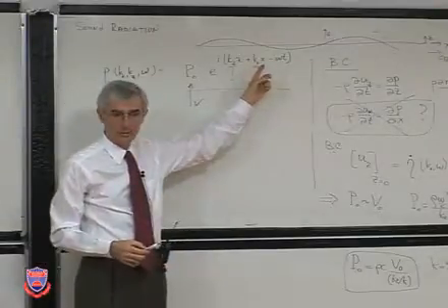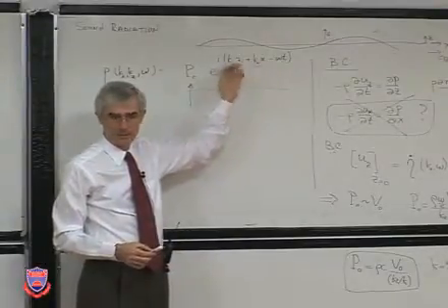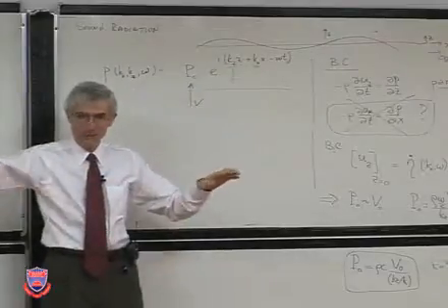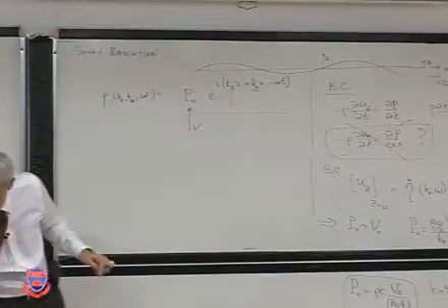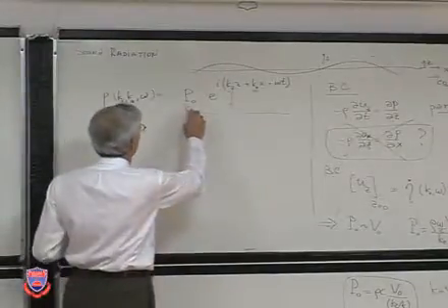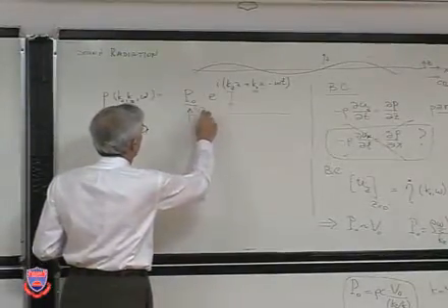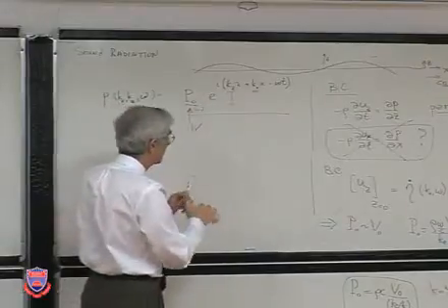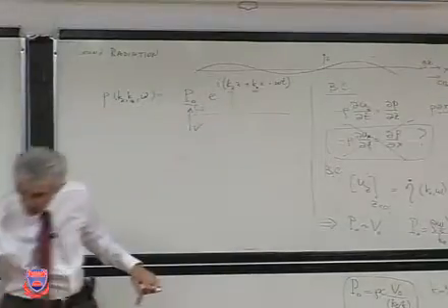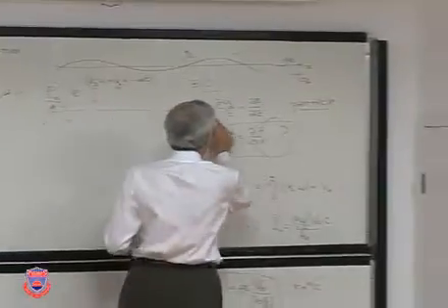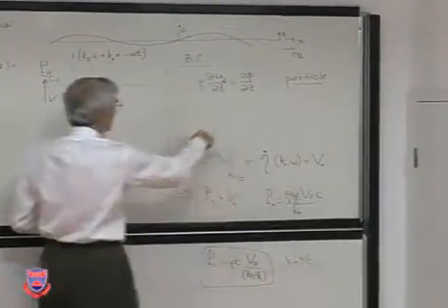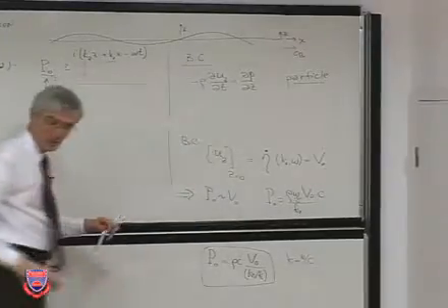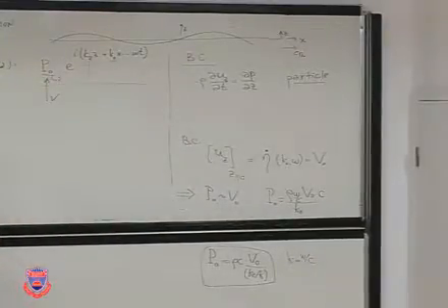We must know, to begin with, kx, because for a given vibration wave number, what is the sound radiation. The two quantities we want to find out are these, amplitude and kz. Amplitude we find out by applying the boundary condition on the surface of the plate.